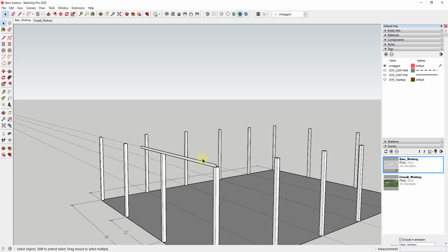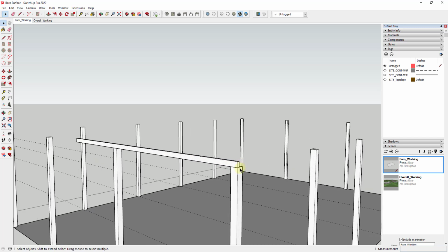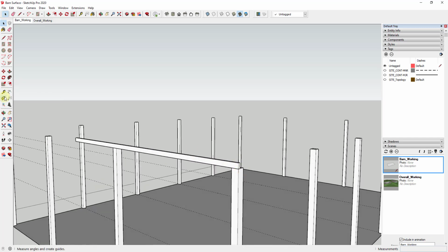this particular tool. So what I'm going to do is I'm just going to push-pull this back. Again, 3.75. No. I'm going to push-pull this back 1.75 inches. And then I'm going to use the protractor tool in order to set my slope. So I'm just going to activate the protractor tool, single click here.